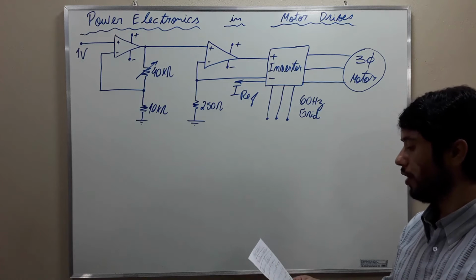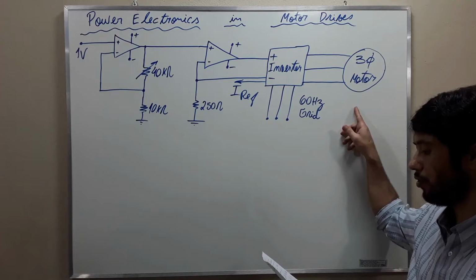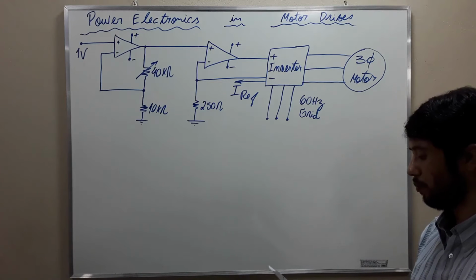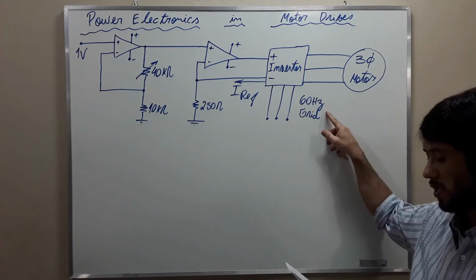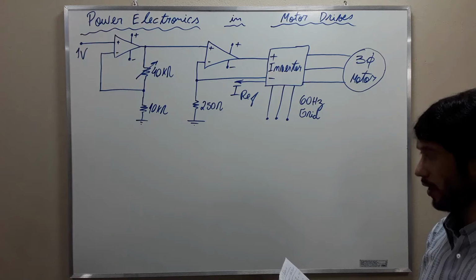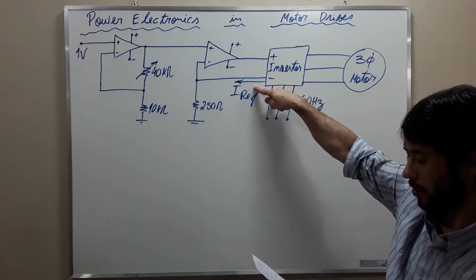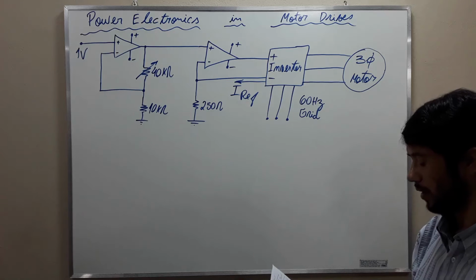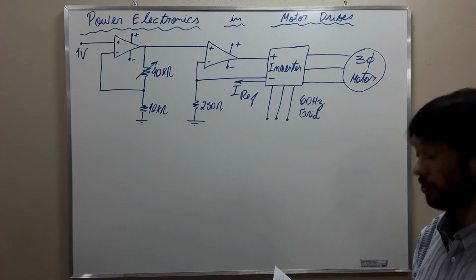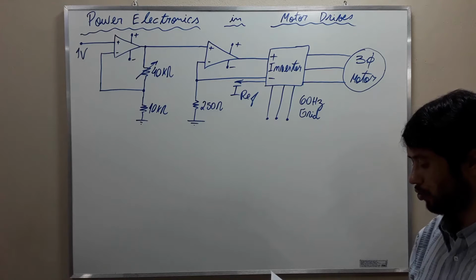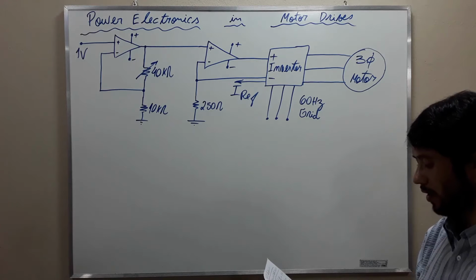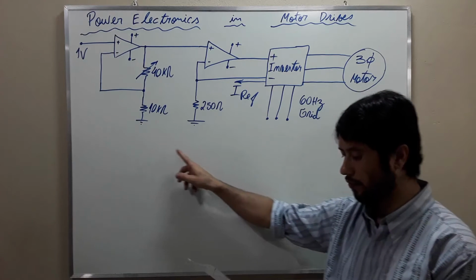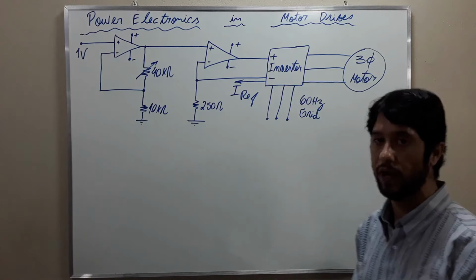The following figure illustrates a three-phase induction motor driven by a frequency inverter whose input is connected to the grid with a constant frequency equal to 60 Hz. By varying the reference current from 4 to 20 milliamperes, the motor speed of rotation varies linearly from 0 to 2000 RPM. The reference current comes from an analog circuit with operational amplifiers in the inverter and voltage current converter configurations.